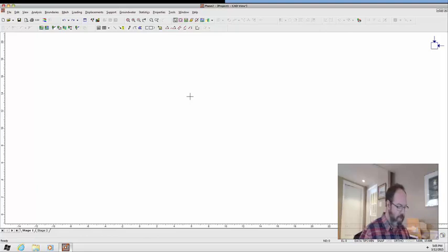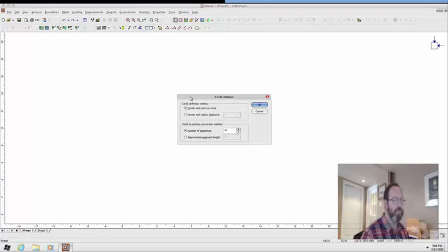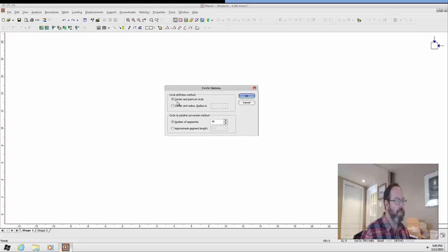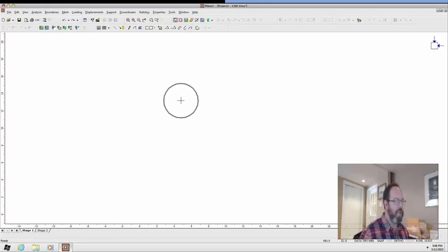I think I'm going to go with a circular excavation. So I'm going to use I and push enter, and then a little dialog comes up. And I'm going to select a center and a radius. And I'm going to want my tunnel, in this case, to have a radius of 2 meters. Meters is the default unit. And I'm going to use 40 segments. So the tunnel's going to, well, actually that's a bit much. Maybe 24 segments. A segment is a small linear section that makes up the circle. And I'm going to center this at 0, 0.